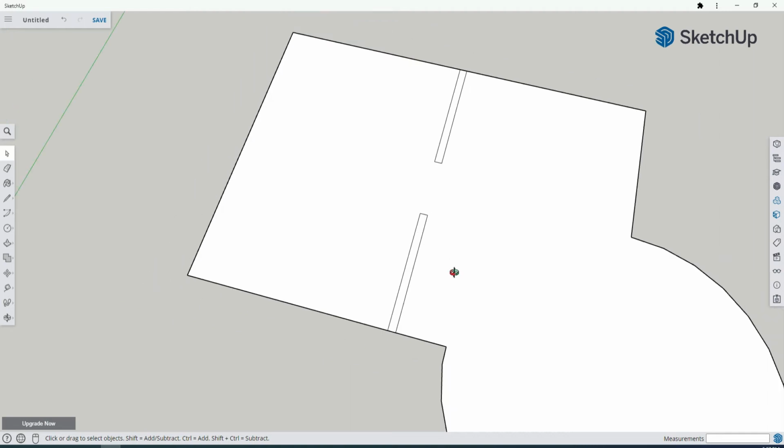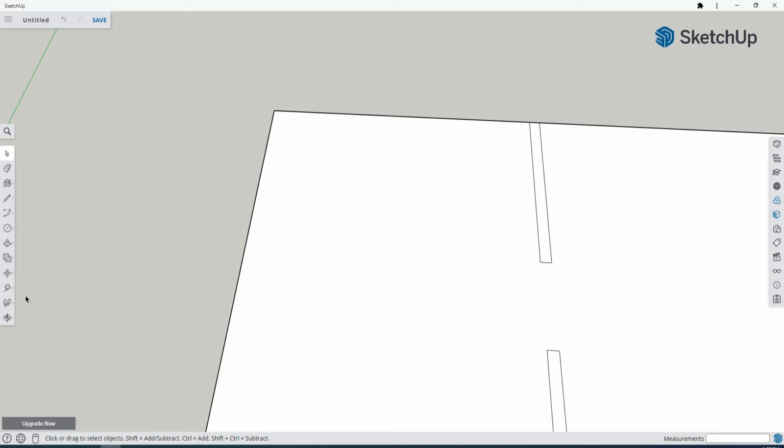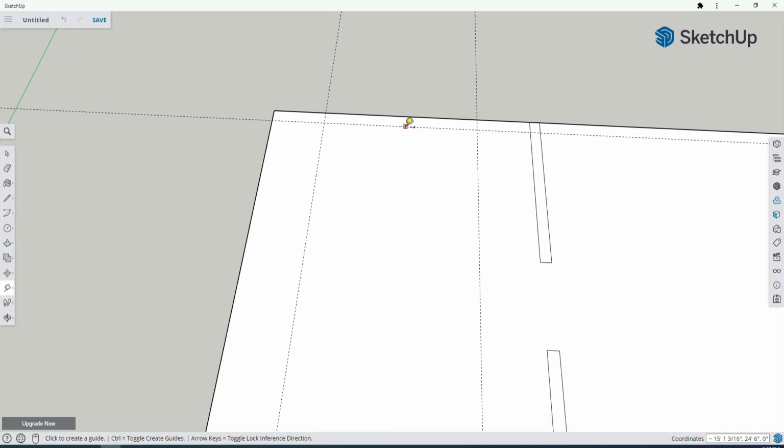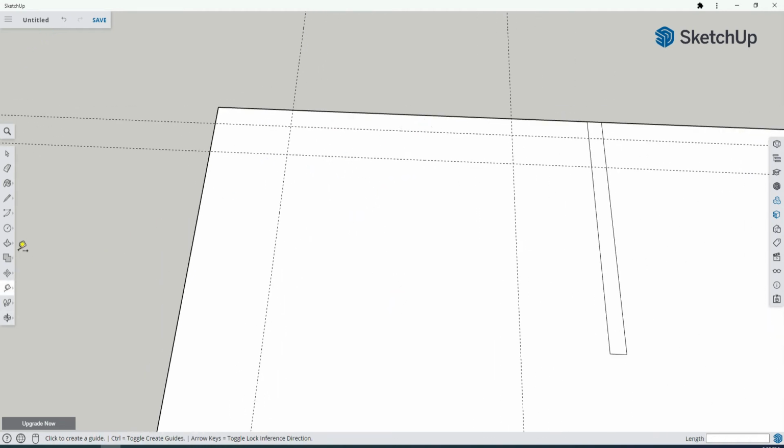Perfect. The measuring tape is how I start to sketch in furniture too. So let's say I want to add some kind of sideboard table off of here. I want it to be maybe 6 inches from the back wall and 2 feet from either side here. So just typing that in, and maybe it's 18, oh, not that, 10 feet, not that, 10 inches. Let's call it 10 inches deep. So blocking that in there, and voila, I've kind of sketched out my rectangle.